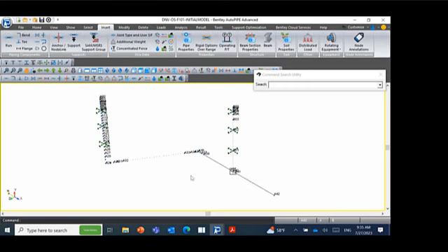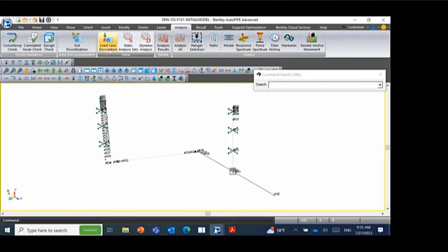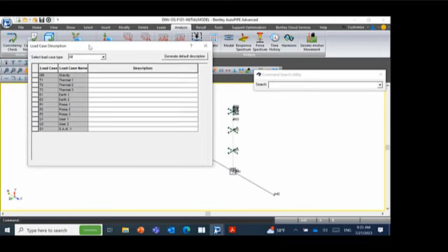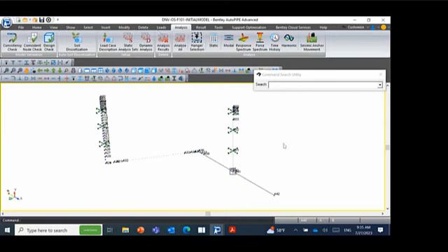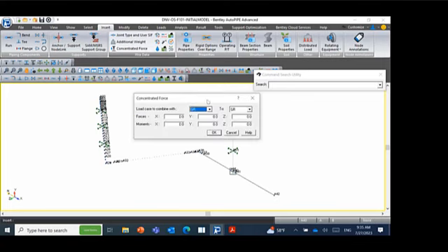When you are defining a load, remember, you have thermal and pressure. Usually, by default, you have gravity, thermal, pressure, and you can declare earthquake or seismic anchor movement. But talking about user, it is an external load. It could be any load you consider, for example, an additional weight and concentrated force.